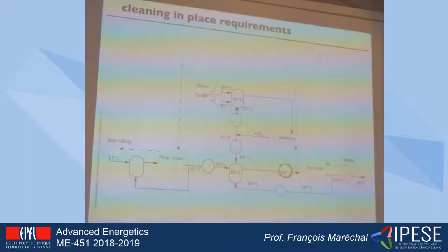And I'm going to satisfy this demand by, on the one hand, preheating the cooling water that is entering here, which is also raw water, that is going to be used in order to do the final rinse. I have a recycling here, just because I want the water to be clean. And then the water that is leaving here at 35 degrees C, after having cooled down the bottles, will be heated to 60 degrees C, because they need to reach the 60 degrees C here.